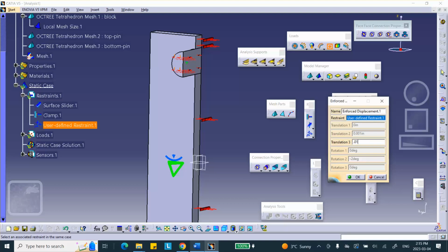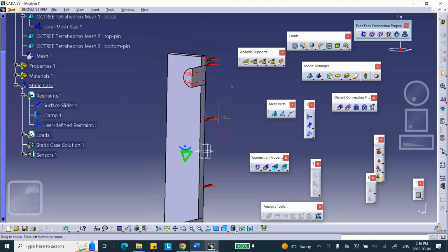0.01 inches. Now, if you see any numbers here, these are from the last time that I ever used this enforced displacement. Unfortunately, these things go away. And if they're confusing you, just zero them out before you go. And there's a -2 degrees. Remember, we did problems like this where we had to rotate a beam by 2 degrees. These are coming from 3 or 4 weeks ago. We say, okay. And hopefully we didn't forget anything.